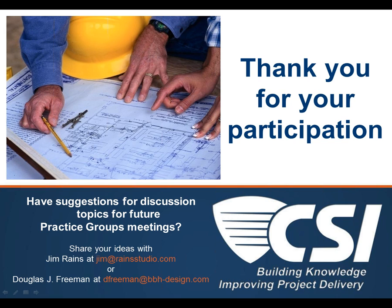What I would suggest you do is circle it, put a question mark by it, and note, this varies from the contract documents. Contract documents say it should be 3 feet, you've got it at 2 feet 8 inches. What's going on? That way you don't take on ownership and responsibility for something that you contractually are not obligated for. So I just wanted to throw that out before we got off the call.